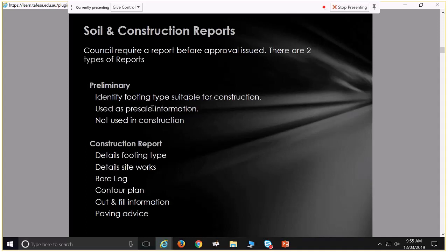But that's also much like what you see as a concrete pier that goes underneath either a timber pier or a steel pier. If you've got deeply reactive soils, one way of getting around that, to still have isolated pier construction like this, is to just produce much longer piers. So you auger down deep into the soil. When you've done your bore logs, you're looking at your soil, looking at, okay, it's reactive, not very reactive. Auger all the way down into that not very reactive soil.